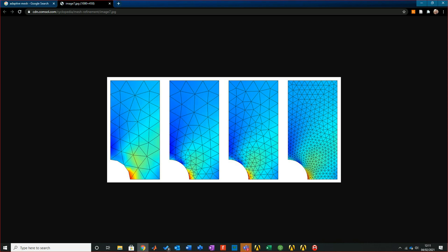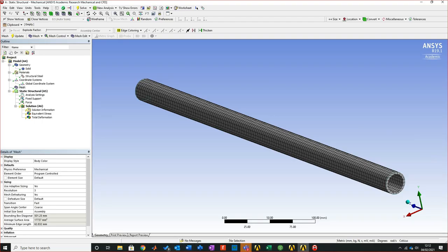Now what you can do is you can actually say to the system, where there's very little activity occurring around the stress limits, keep the nodes at a large level. However, wherever there's larger stresses occurring, reiterate that even further. So loop it, make the resolution greater. If this was 2mm gap between each node, you could make that resolution twice the minimized size. If I make that resolution 5 times, you make it 5 times smaller, and you end up with something a little bit more like this. And it allows it to be adaptive.